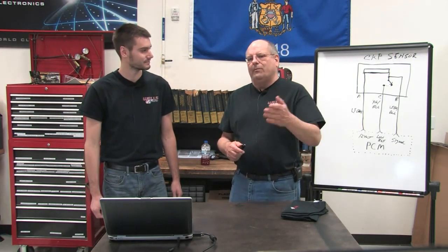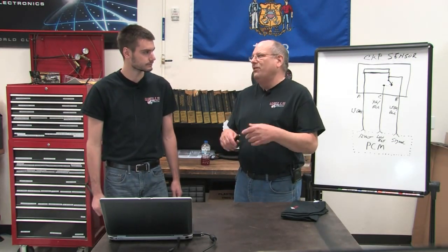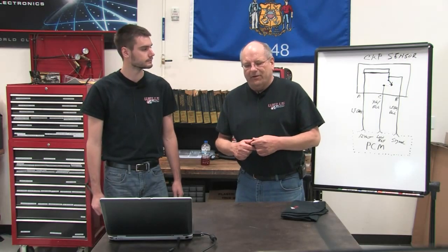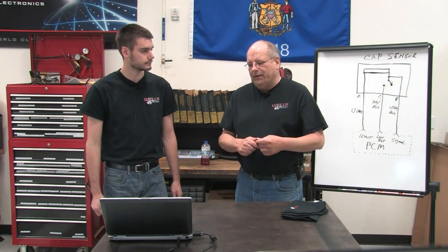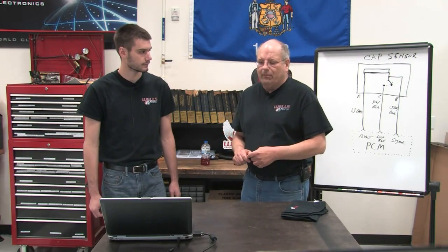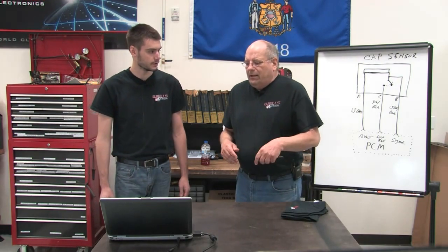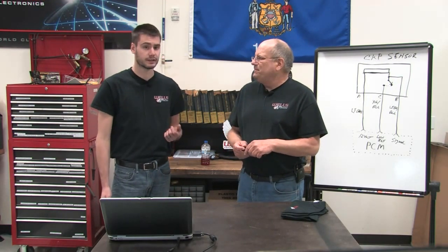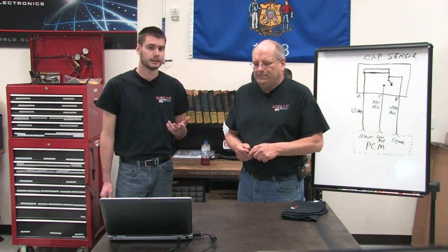I'm sure you pull those lines off the power steering. It's never easy, and you can create a big mess. So there's a good tip for you: just slide it back. You don't have to pull it up completely off. Right.